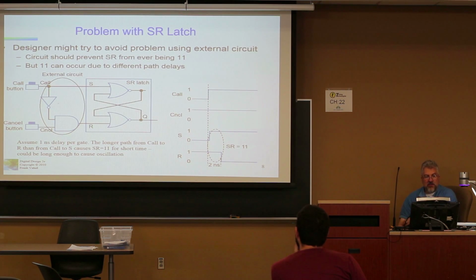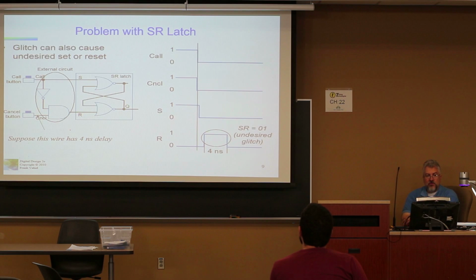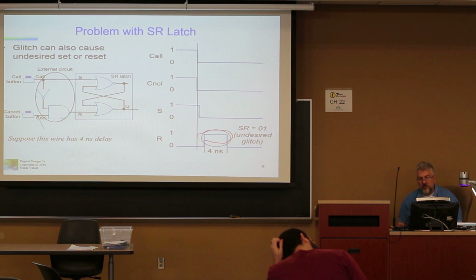In this case, you follow up with a OR gate. I'm sorry, with a NOT gate going through an AND. And again, we have a problem with gate delays. And so we can get, remember that glitch we talked about in the last class? Because of these gate delays, you might have an additional little bit of information come in.